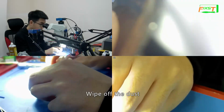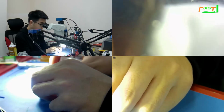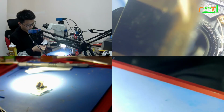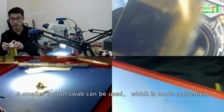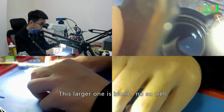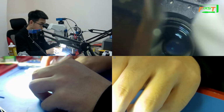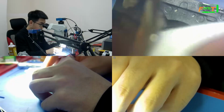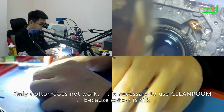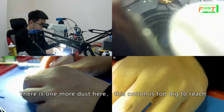Wipe off the dust. A smaller cotton swab can be used, which is more convenient. This larger one is blunt, not so good. Only cotton does not work. It is necessary to use clean room cloth because cotton sheds fibers. There is one more dust here. This cotton is too big to reach.